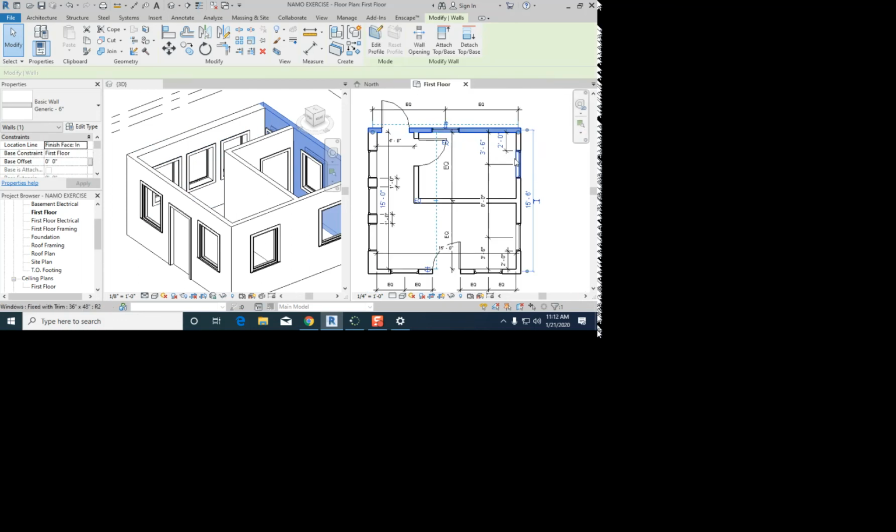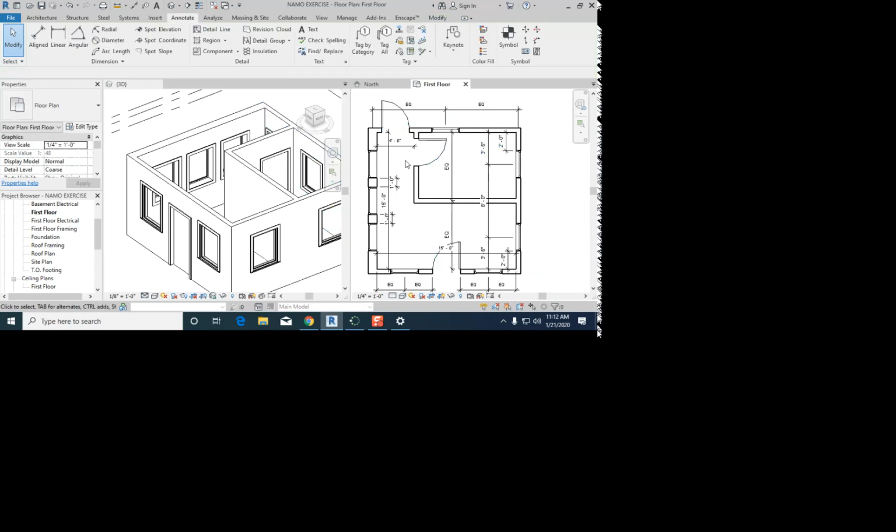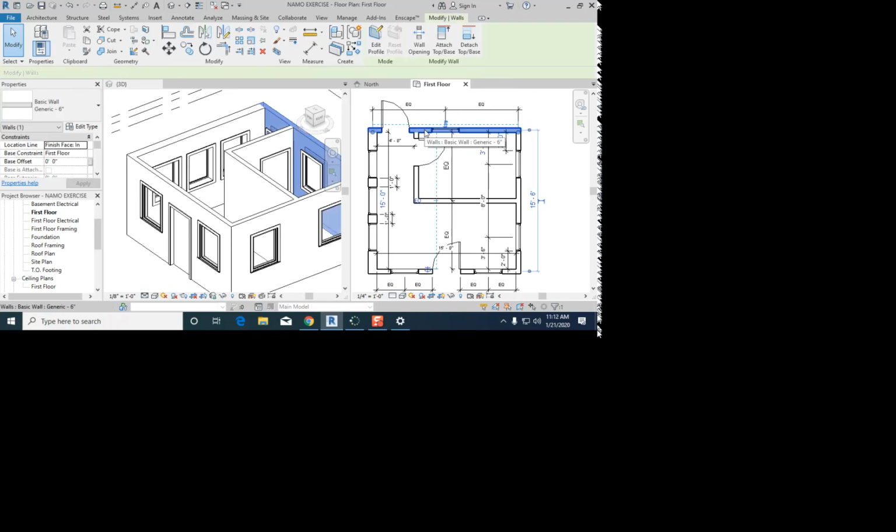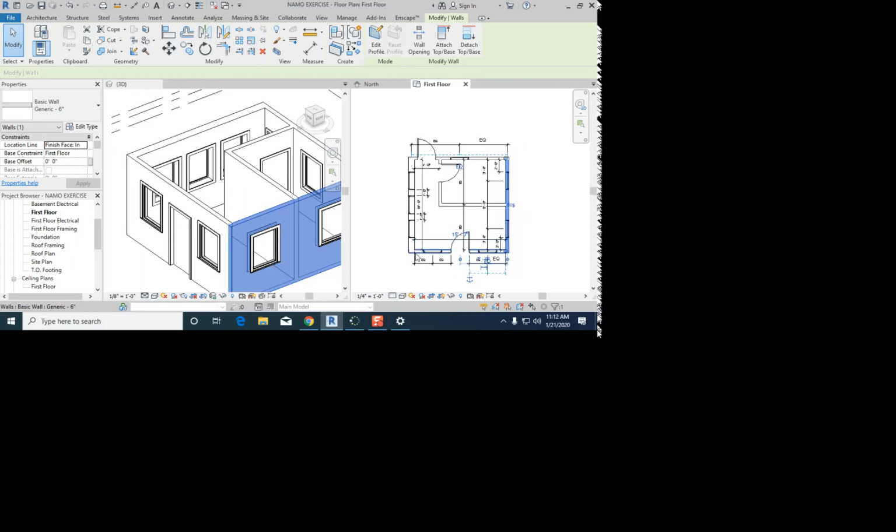Let me see. I'm going to hit Control on these two. No, you have to do it individually. So you would just have to go through and flip the face. You wouldn't be able to do both the faces? No, you have to do it individually. I'm not sure why it doesn't let you do more than one at a time. But so go through and flip each segment.